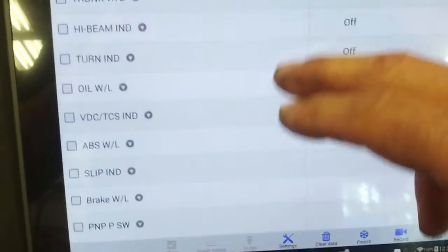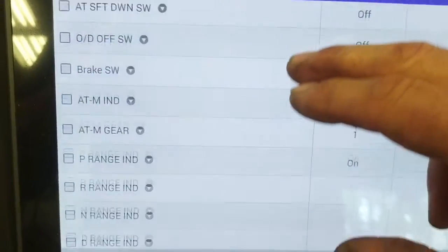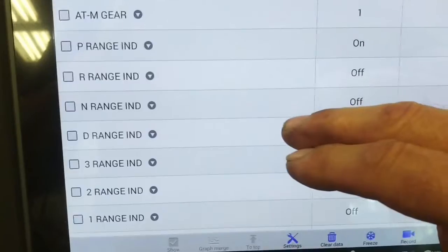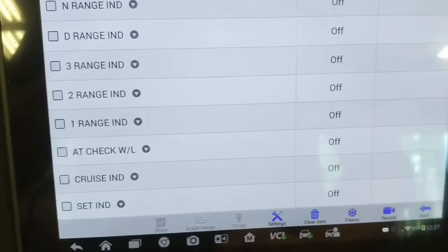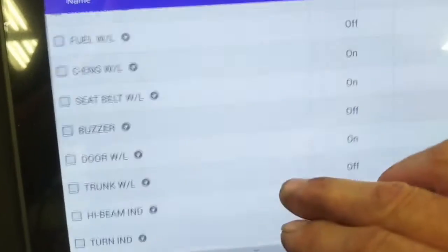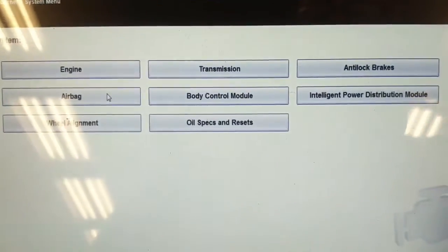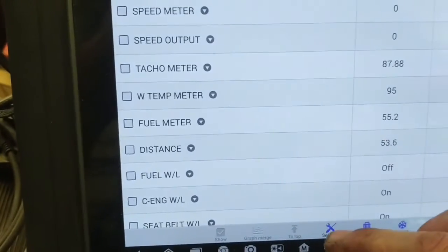Because apparently the ambient temperature sensor occasionally will fail and indicate that it's colder than it really is, so it disables the AC. And I don't see it there. Sad thing is, this module is not even available to scan on the Snap-on scan tool. Neither of the scan tools would support auto ID of this vehicle, so can't really fault them for that.